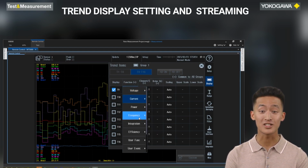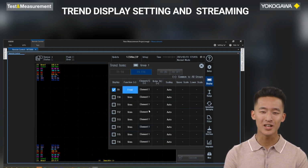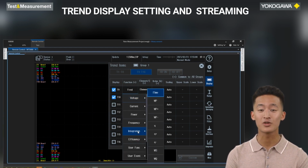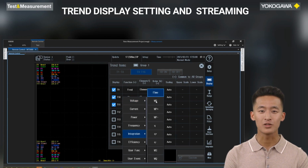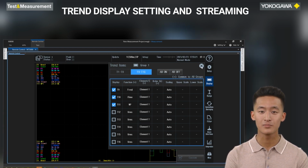Let's configure trace 9 for frequency of current, trace 10 for time of integration function, and trace 11 for energy. We can also select particular element from the available inserted elements in WT5000 for measurement of trend graphs. Once after setting the traces, we can close this window and click on Display.